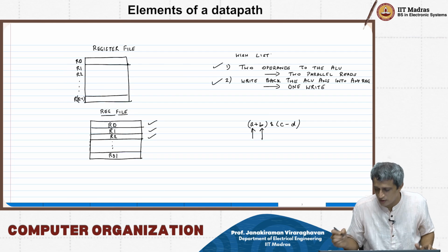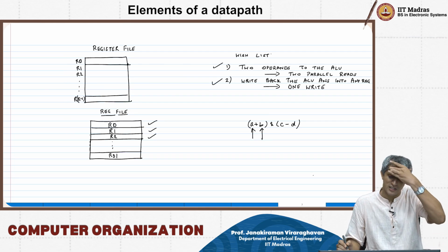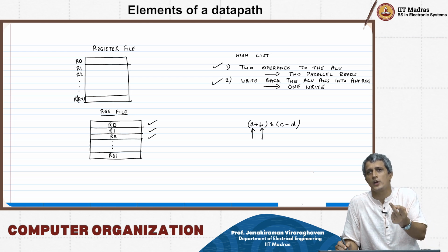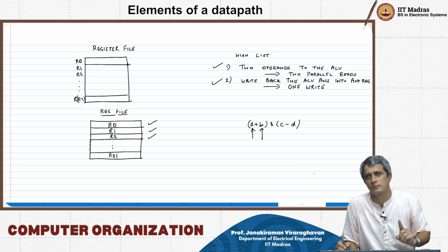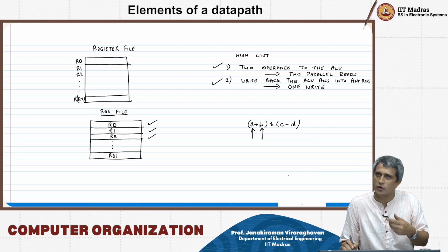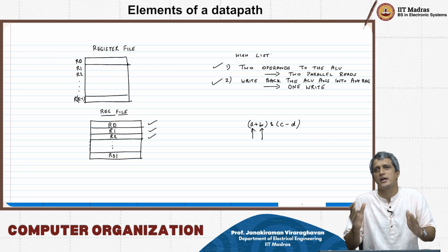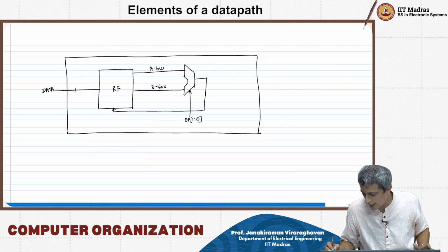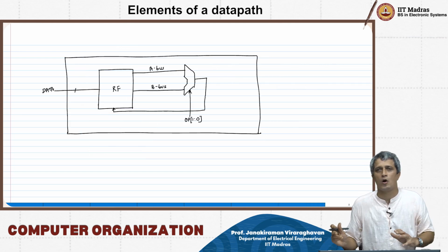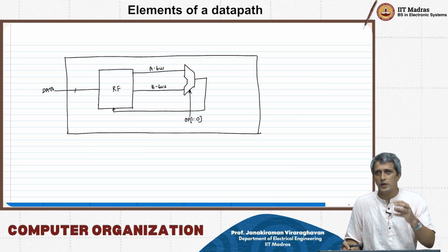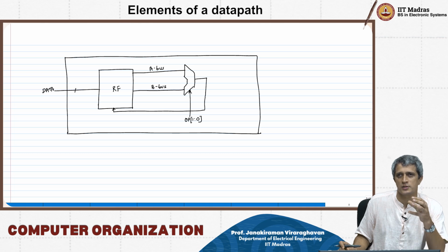So this is the advantage of combining these register files and building a register file with these kind of features. So this kind of a register file is a register file with 2 read ports and 1 write port. Okay, you can technically have 3 read ports, 2 write ports and all that. It depends on how many wires you are able to implement and allocate in parallel in order to do this operation.